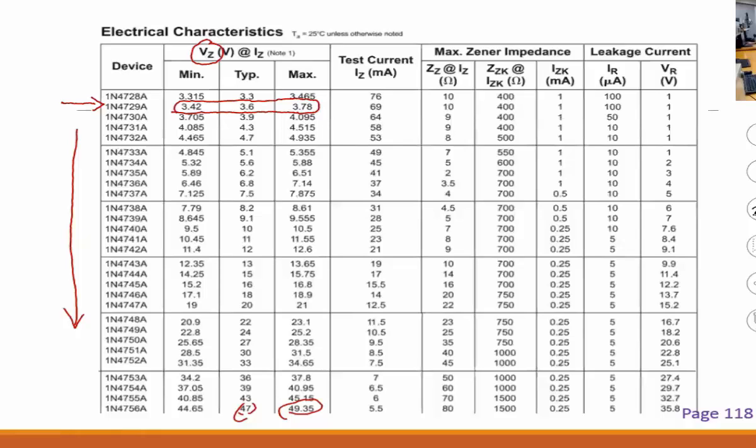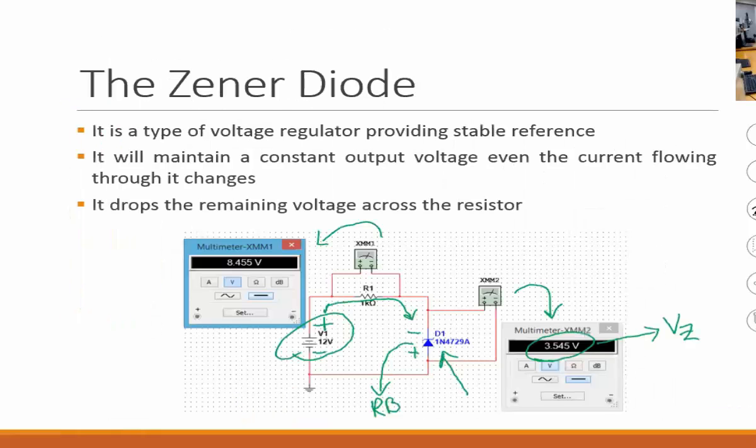Maximum reverse. That's not reverse. Is it minimum reverse? Is that considering the amount of reverse voltage? It's considered, so this voltage is the voltage you will see on a Zener diode under reverse bias if the source voltage exceeds the Zener voltage. Remember, what is a voltage regulator?